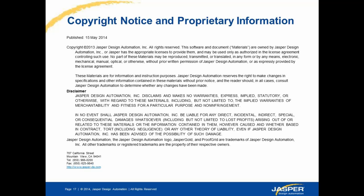And the idea of a bounded proof is not to tell you for sure that this is the depth at which you will get a full proof. If that was possible, we would have given a full proof anyway. So the fact that you have a bounded proof means that it is a depth till which, if you run the engine to this particular depth, then you would have hit all RTL cover points which impact this particular property. And you get a much better confidence in the bounded proof or the depth you have run it to.